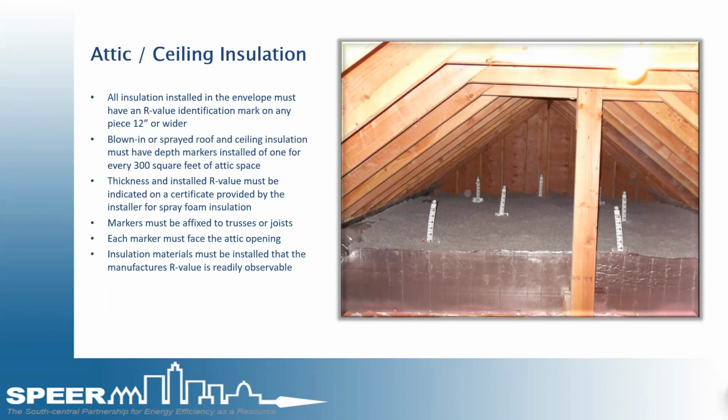Each marker must face the attic opening, and insulation materials must be installed where the manufacturer's R-value is readily observable. That's kind of for flat ceilings. If you're doing batts and you've got to see it from the floor, have the R-value readily available.